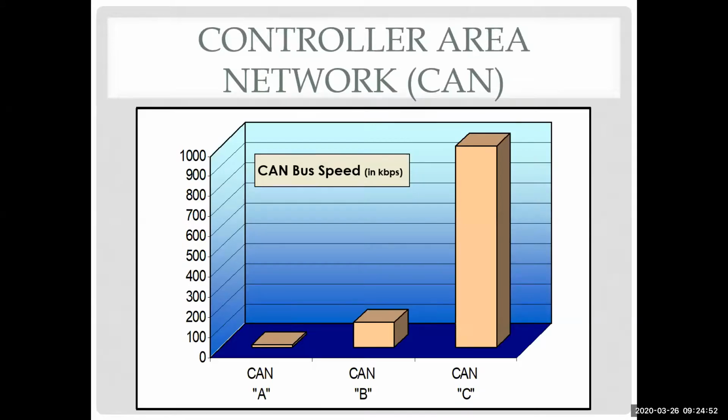So here's an example going from CAN A, where boy, we thought we were fast, to CAN B, which is still used by a lot of manufacturers. Like I said, GM still uses CAN A, to CAN C. Now we also have a CAN D. Now, if you work on Mercedes vehicles, Mercedes makes this really confusing because they title their CAN D diagnostic CAN B body CAN.